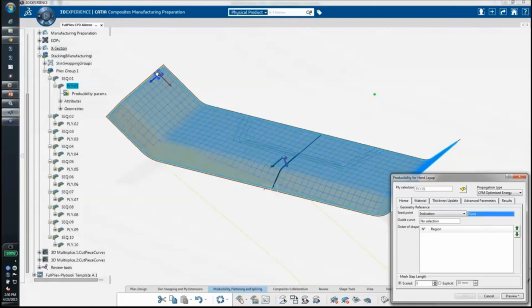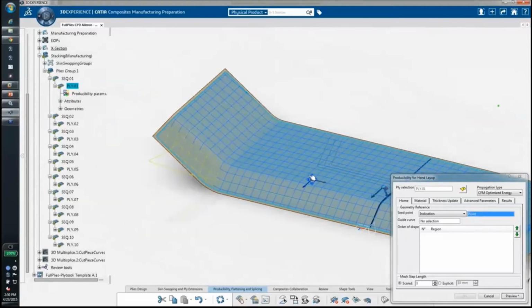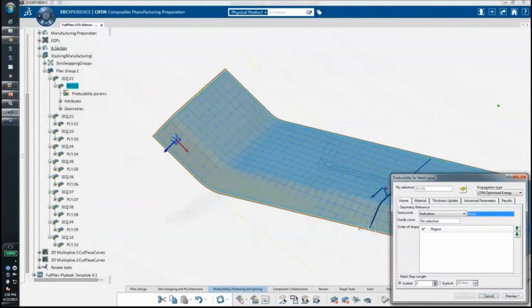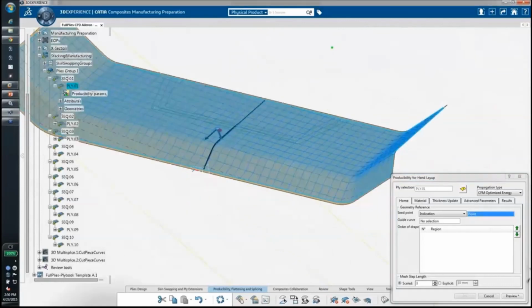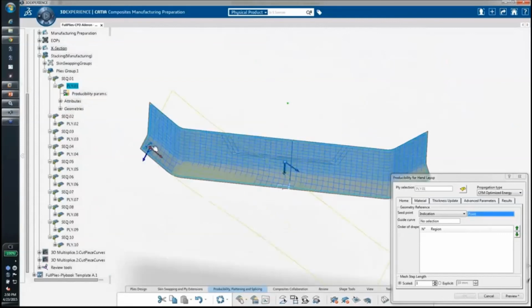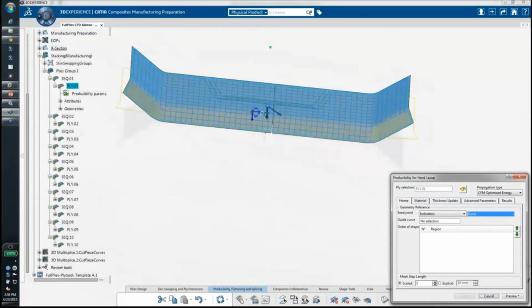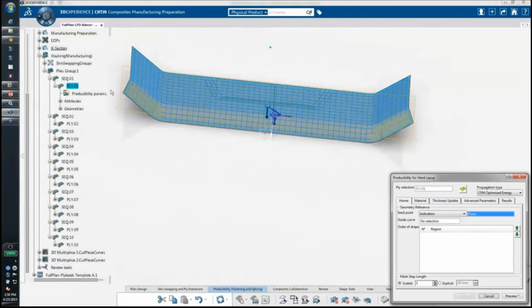So I can push it right to the edge. And so you can see that I have some yellow shearing here. Well, if I take it and let's just throw it up in the corner here, it's actually showing a different flat pattern because I'm over here producing from this edge, the straight edge, the pattern's straight on this edge, and it's got that joggle on the right edge. If I go into the middle, it's going to have a little joggle here on both edges.